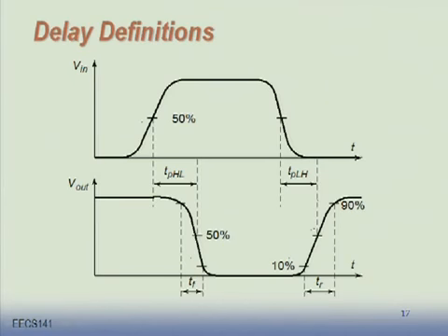But there is a slightly more important thing. Fundamentally, I want to find a propagation delay of a chain of gates. Their propagation delay is better not being dependent on if they have different V output highs and V output lows. Better have it defined to something that we can just add up.